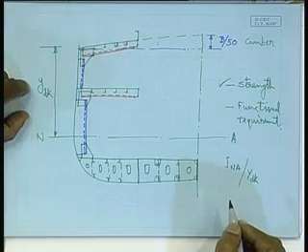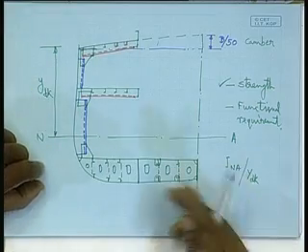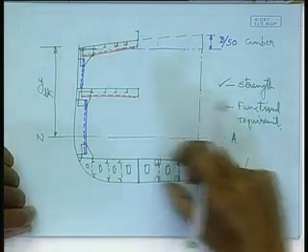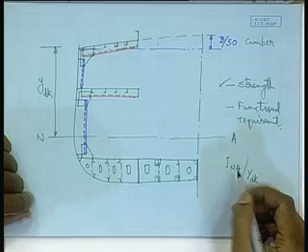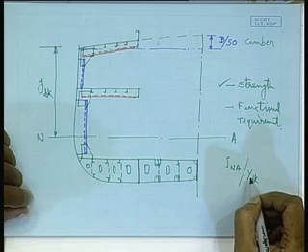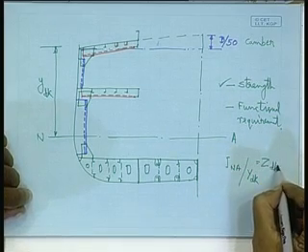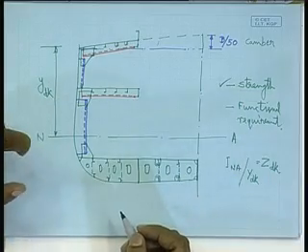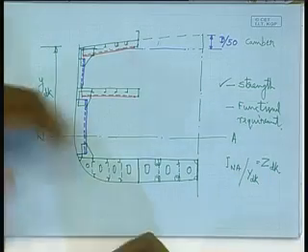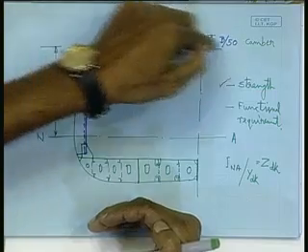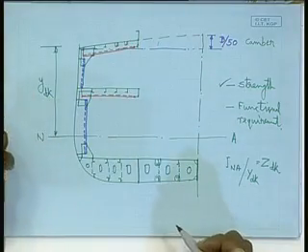Y deck is always bigger than y keel, because you have a higher concentration of structural members below. So, this is always the minimum value. So, this is my so called Z deck, the section modulus with relation to the deck plating.